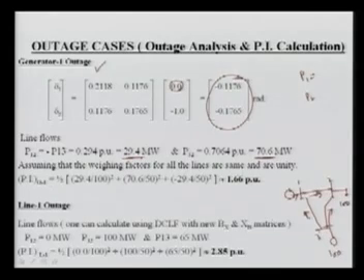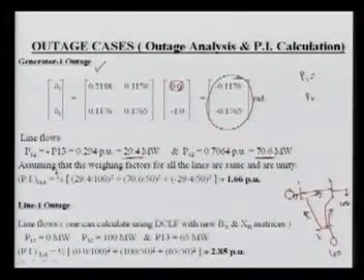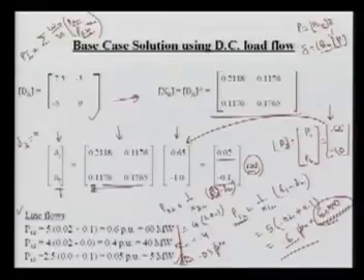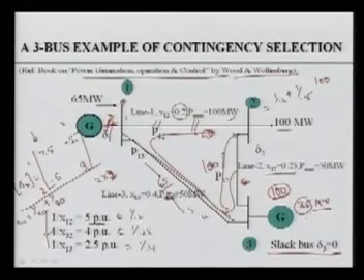Again with the same real power flow performance index we are using, and we are using this WM value as unity. We are using the exponent n equal to 2, meaning the square term. So we are dividing by 1/2. Now we are assuming the line rating. You can already see the line ratings I have explained here. The line rating of this line is 100 megawatt.